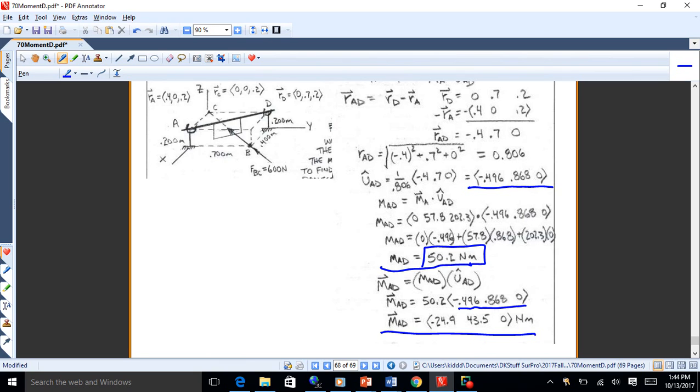Okay. And if we know the axis, it's okay to answer just the scalar torque? Yeah, it depends. Quite often you just need a scalar, because that is the torque around that axis. It's what the moment is about the axis, right? So the first thing you get is a scalar. But if you need the vector, it's easy enough because you already have a unit vector for the axis anyway. So just multiply through by the magnitude, and you'll get a vector if you need it. Okay.